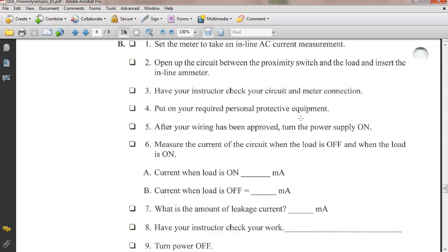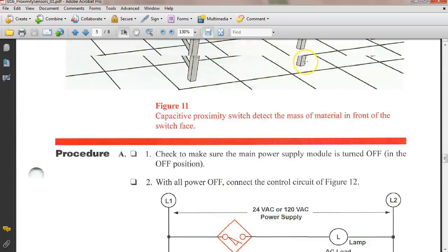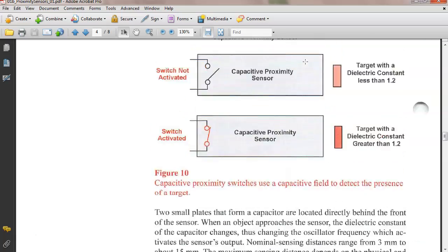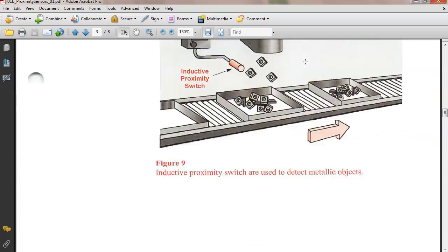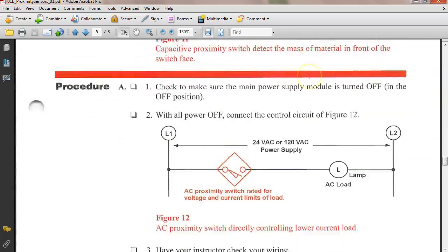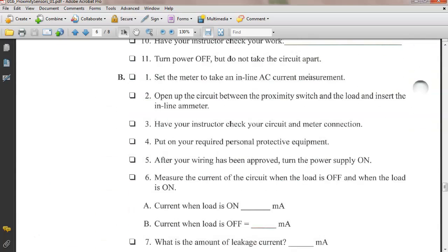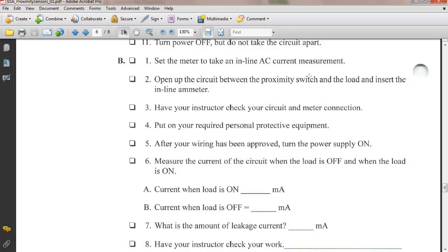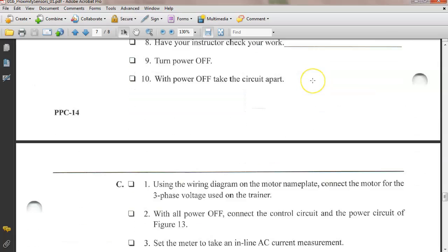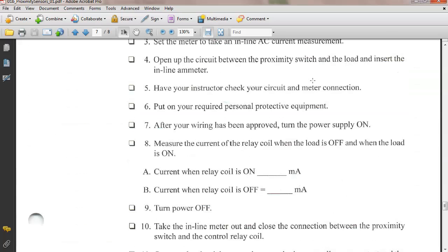So we have different currents we're going to measure. And this should have been explained. So holding current, leakage current, holding current, and this will be explained in the data sheets. So be careful here, because this is where you might blow the fuse in your meter, right? And each one of you should have your own meter.